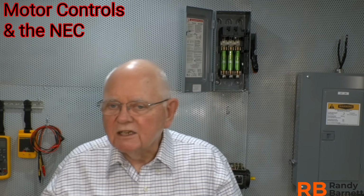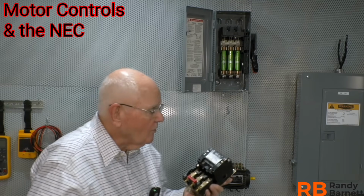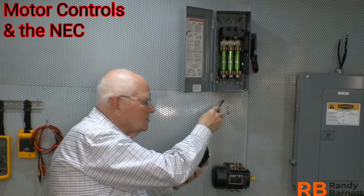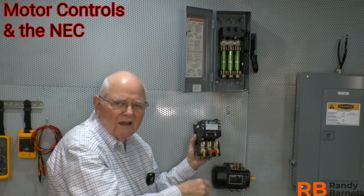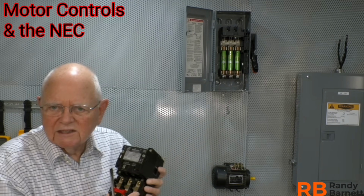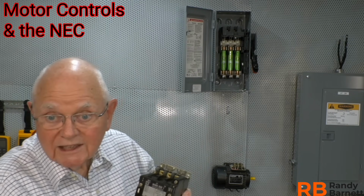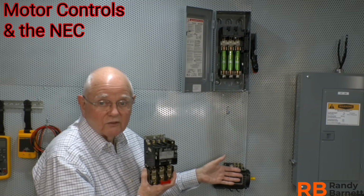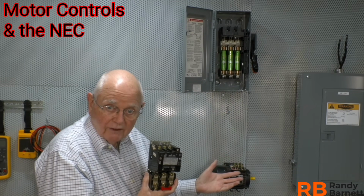So realistically, if I'm running, say, a 10 horsepower motor, I'm probably running 30 amp fuses up here. I've got 10 or 12 AWG wire coming down to the top of my motor starter, and those same size AWG conductors going on down to my motor. I said just a minute ago that the fuses are designed to protect all of this wiring downstream. And that's true. What protects the motor? The overloads on the motor.